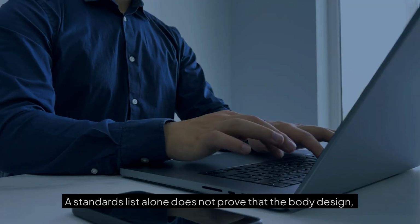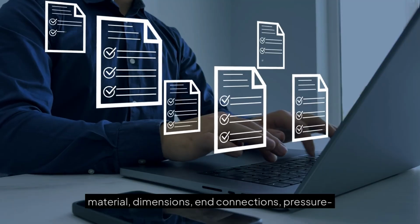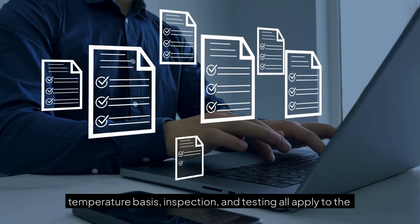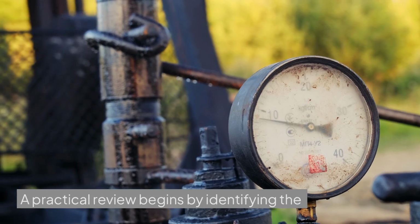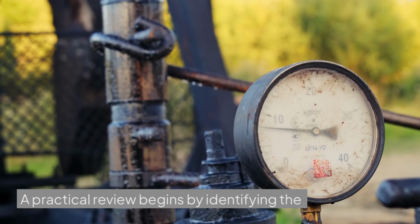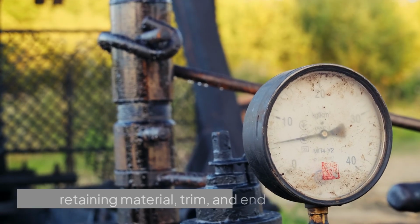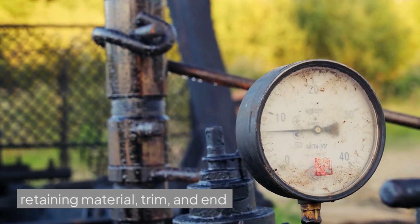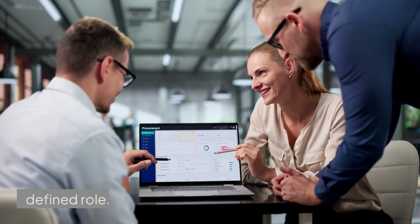A standards list alone does not prove that the body design, material, dimensions, end connections, pressure-temperature basis, inspection, and testing all apply to the same configuration. A practical review begins by identifying the exact valve, size, pressure class, pressure-retaining material, trim, and end connection. The buyer then assigns each reference a defined role.